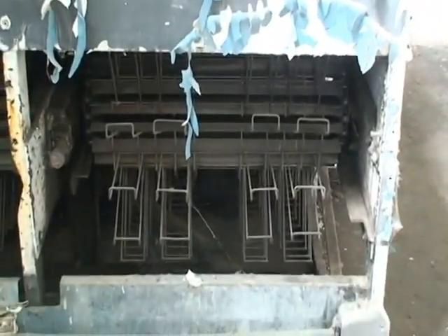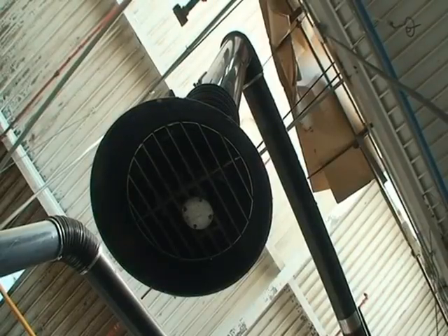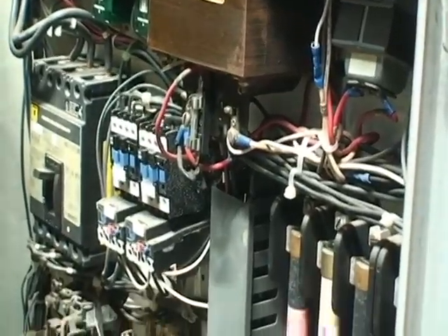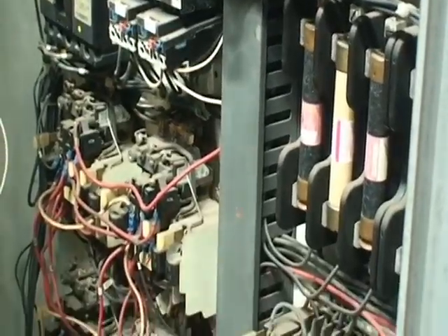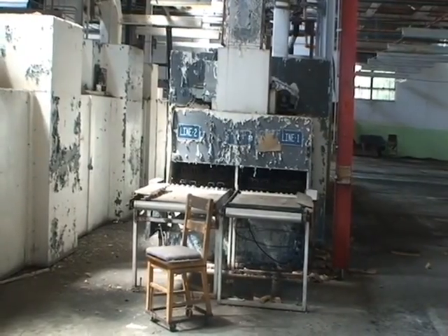One of the unique things about amosite being used around high heat is that it will not take water like chrysotile containing materials will, and that's one of the essentials in work practices, so always keep that in mind. Here's an example of air cell pipe insulation. It's a paper insulation. It's got this characteristic appearance. If you look at it on the end, it looks like a corrugated cardboard box.